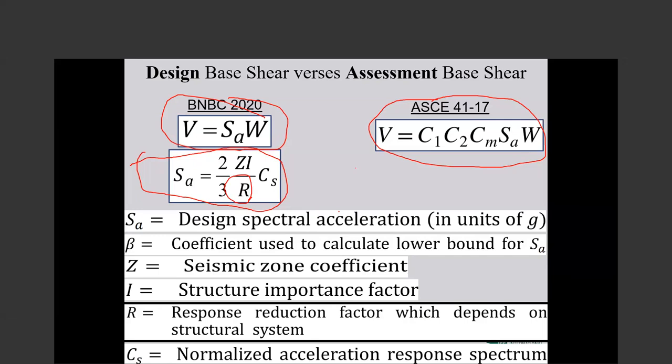It limits the R value. So if we want to divide the elastic base shear of the building by a value, if you use the one that is in the code, it's dangerous. It's killing people, because the real R value of this building with this much deficiency is not the same as that system based on all the requirements of the detailing code.